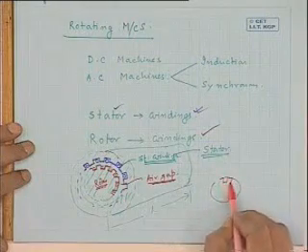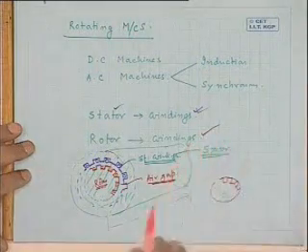The last point, after which I will close today: generally the stator or rotor structure of these machines is not obtained from a solid block of iron. There also stampings are used. You have several thin circular plates, and you keep one above the other to make the length of the machine. Similarly, to avoid eddy current losses in a transformer, they use stampings stacked together, and slots along that length are where you can put the conductors.